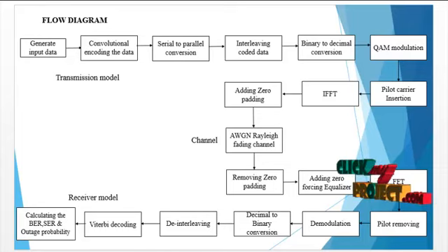Here the modulation schemes can be independent of the specific channel being used and can be chosen based on the channel requirement. In fact, it is possible for each individual subcarrier to use a different modulation scheme. The role of the IFFT is to modulate each subchannel on the appropriate carrier. This is the zero padding. Implementing the zero padding consists of appending zeros to a signal before the transmitter sends it over a channel.